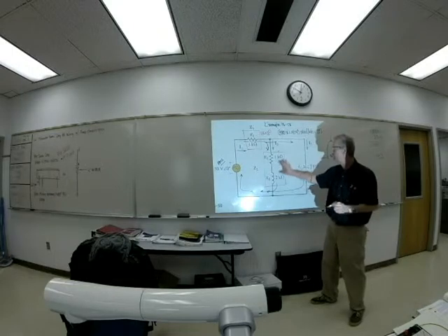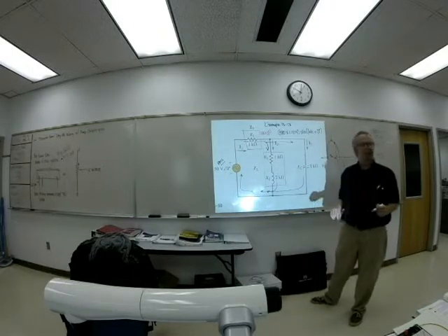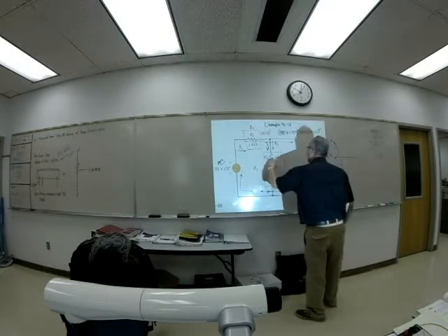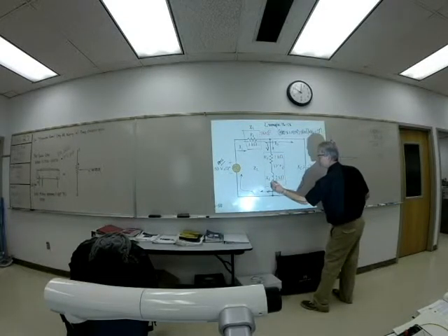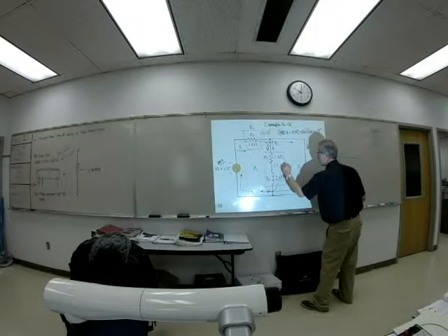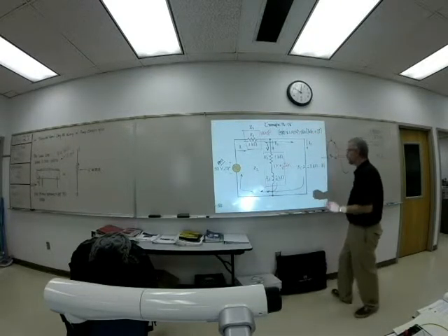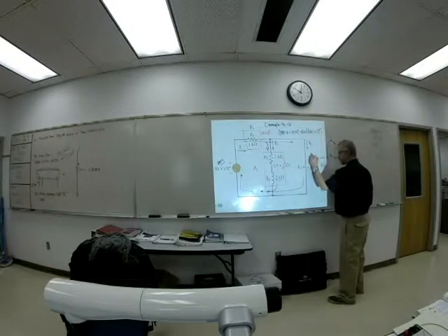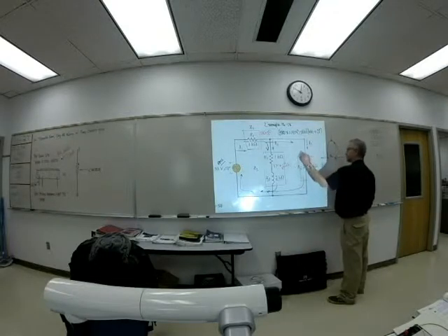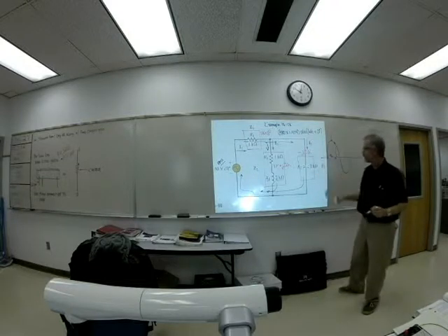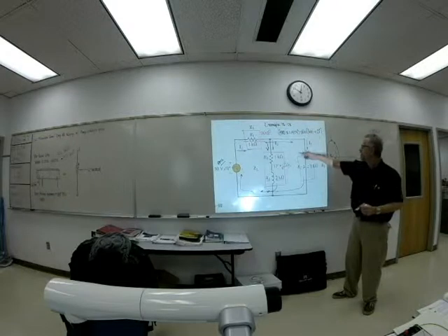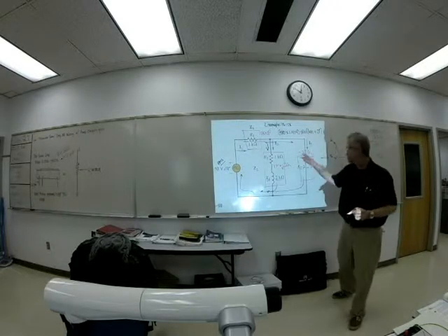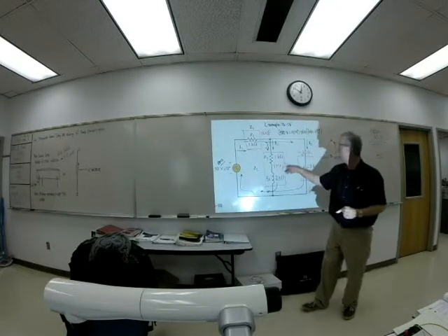This block, because they're in series, we can simply add them together. That gives us 1K plus j2K, and it's plus j because we're looking at an inductor. And this little fella over here is minus j2K, because he's a capacitor. His reactance is in the downward direction, so we use a minus j to indicate it's 180 degrees away from the plus j we have here.